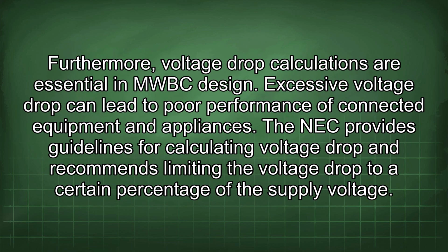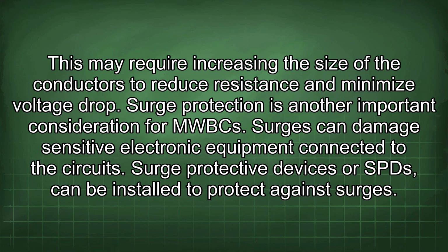Furthermore, voltage drop calculations are essential in MWBC design. Excessive voltage drop can lead to poor performance of connected equipment and appliances. The NEC provides guidelines for calculating voltage drop and recommends limiting the voltage drop to a certain percentage of the supply voltage. This may require increasing the size of the conductors to reduce resistance and minimize voltage drop.